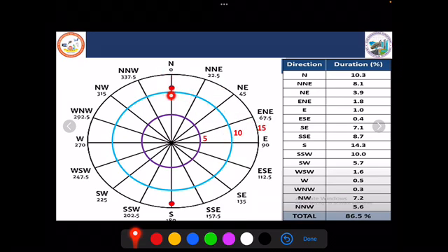So along the north direction, between 10 and 15, just past the line of 10, you mark a point. Once that is done, next check the north-northeast, that is 8.1. So 8.1 along the north-northeast direction is between 5 and 10. Between these two lines my next point has to be located.